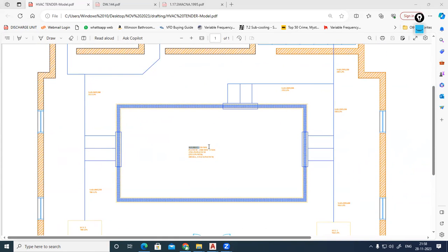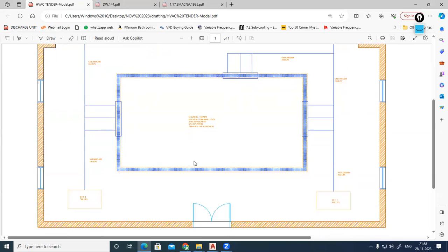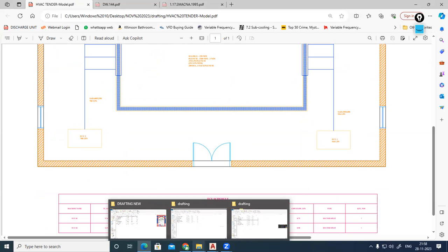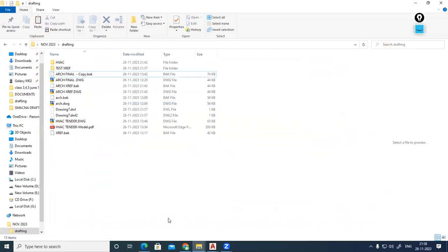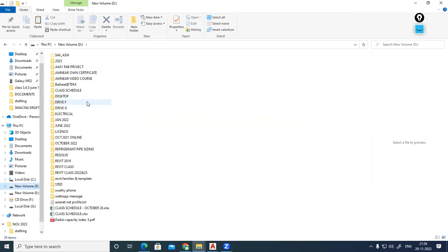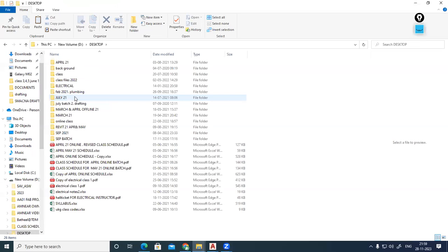See, that's why in reality, when we are selecting the machine, we need condenser entering temperature, entering wet bulb temperature. Then we need bypass factor, airflow rate, and kilowatt, meaning the machine total coil load. But let's say we have selected against this specified data. The model number is FDMRN 50AV1K. I need the actual dimension of the machine. When you are making your shop drawing, you need the actual dimension. So I'm just selecting a technical data sheet for Daikin.